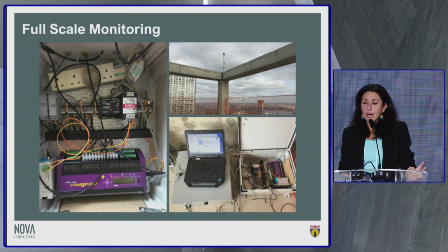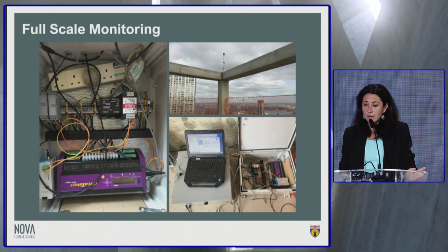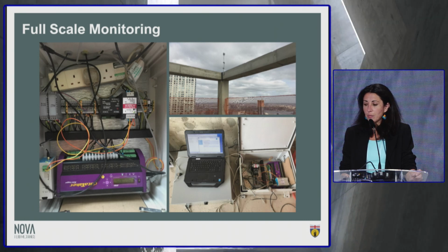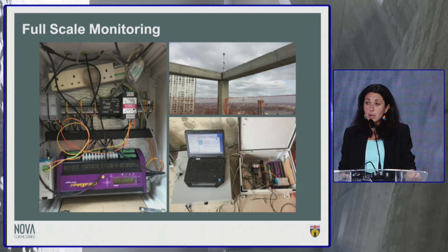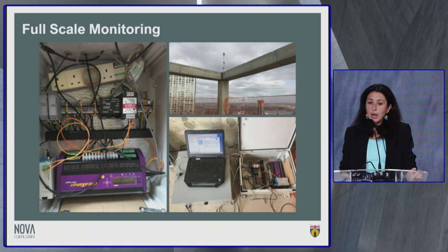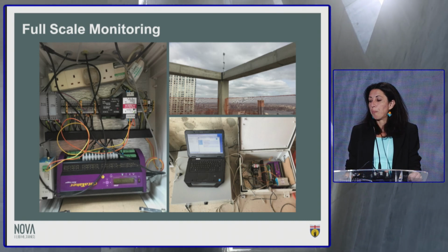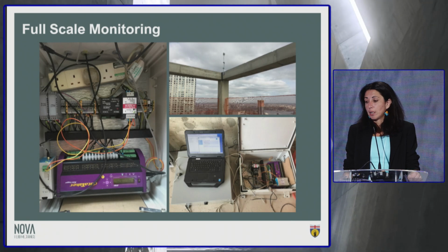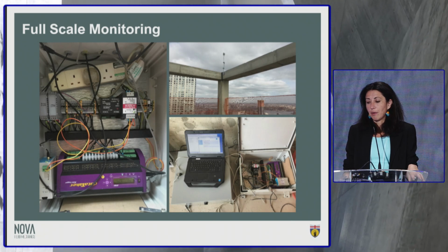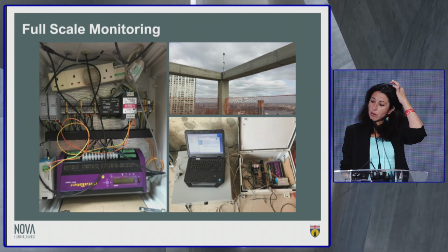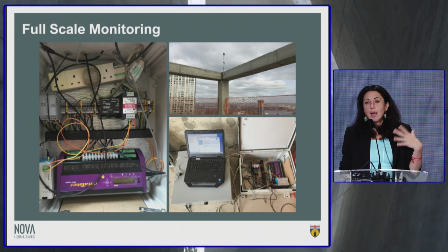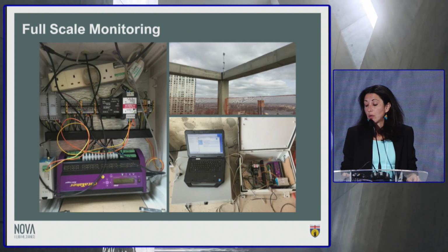Full-scale monitoring will be of great importance. We have now an agreement with the owner of Project X, and as soon as Project X will be completed, obviously within 6 to 8 months, we'll be able to instrument it. That will give us some invaluable data, because we will be able to compare, if we are able to stay there for long enough, the acceleration due to synoptic events with the acceleration due to thunderstorm events. And I believe that we will find that every time the building is experiencing a thunderstorm, it's not moving.